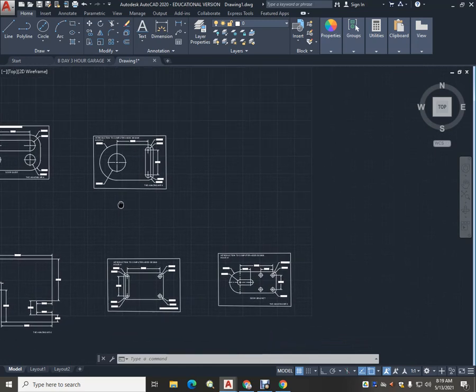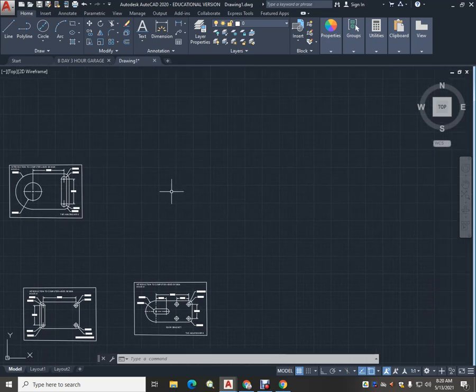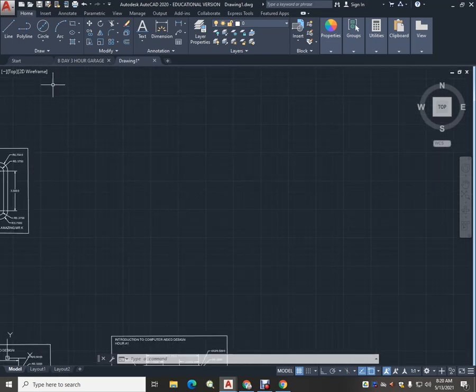And so we have 5. So let's go ahead now and do the next one. Actually, this one's called the Bennett, and it's a T drawing. Looks like a T. So let's go ahead and start that. We'll just get a clean space over here, and start with our line command. Remember that we always want to try to have this line command set at 0 degrees. And this first line is 8 inches long. No. Whoops. 4 inches long for this first part.